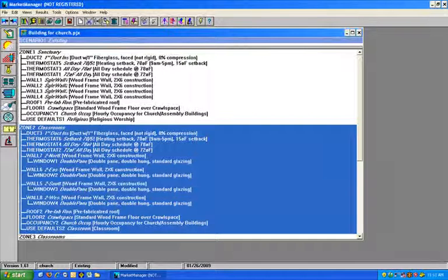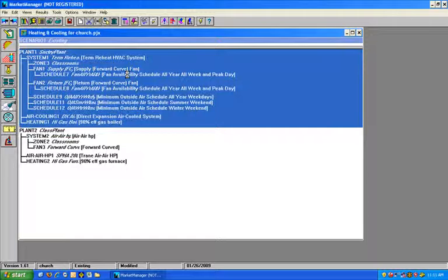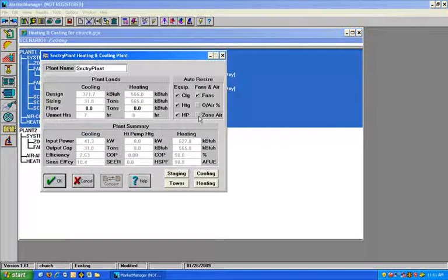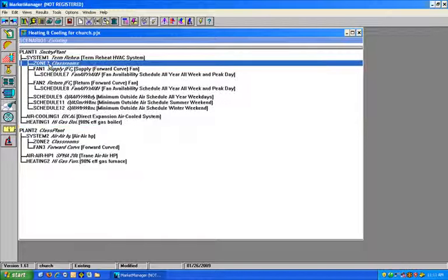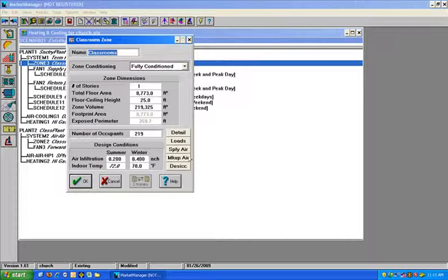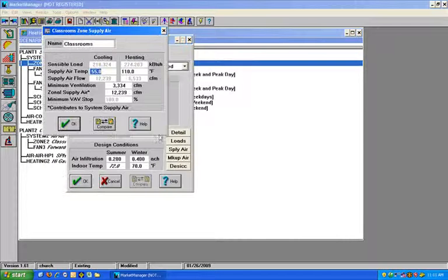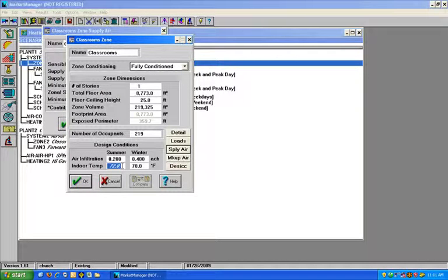If you were not auto sizing the zone air, and I suggest that you do auto size it, but let's say you weren't, then in supply air, see, now this isn't being calculated, right? What if you went and changed this and you decided, well, I think in the wintertime we need to heat to 75.